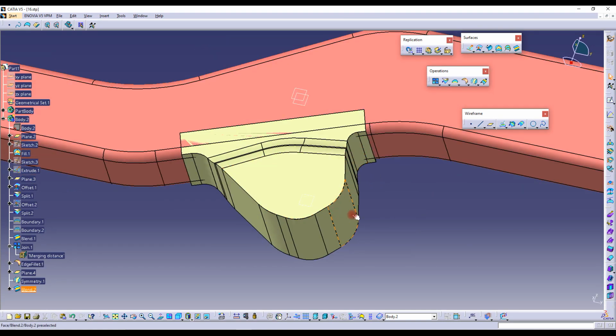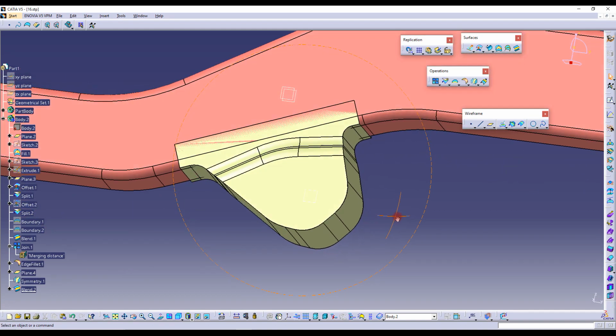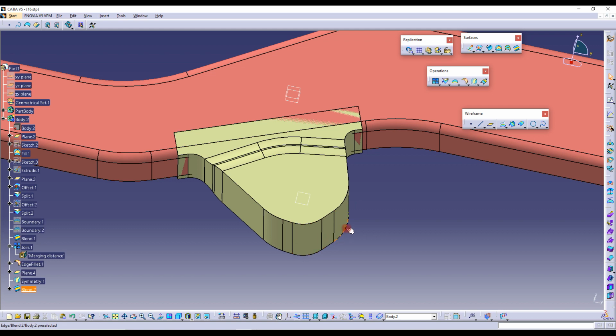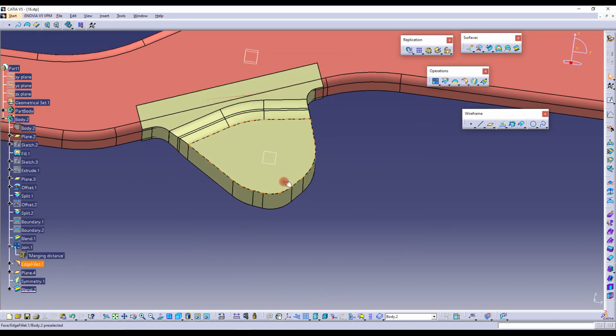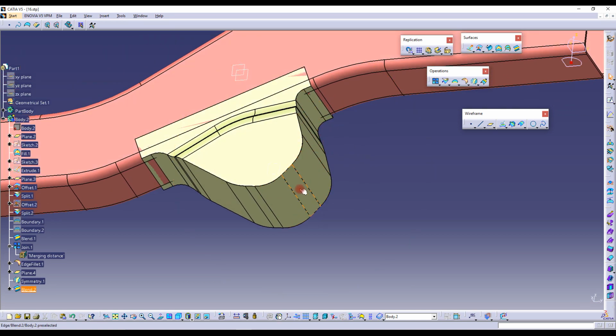Now this surface has totally enclosed the bush inside the surface. But for practical assembly, we require a cutout so that the control arm which has this bush will be assembled from the bottom through the cutout. And also when the suspension articulates, that cutout will allow the suspension to articulate without any interference. So we need to give a cutout over here and remove these surfaces.